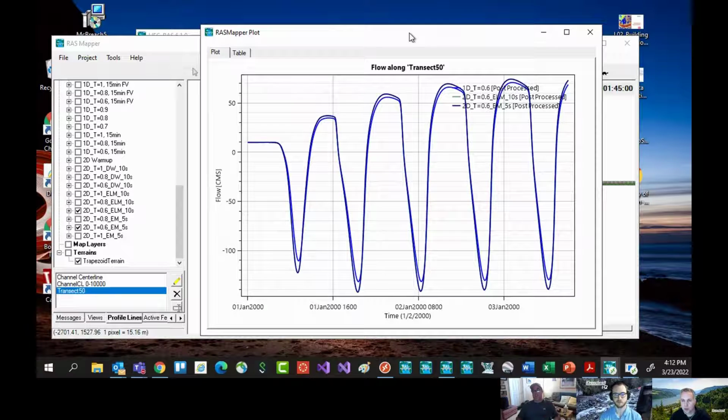If you just put the tidal boundary condition in the middle of the bay or estuary, it's still going to have velocity go in and out, but it might not be quite as accurate. But the important thing is where was the data measured? Was it measured in the middle of the bay? Then of course you use it there. But if it's an ocean gauge, then that's out away from the boundary of the coast. And so I like to add some terrain out in the ocean and then put that boundary condition out in the ocean if it's an ocean tide gauge.